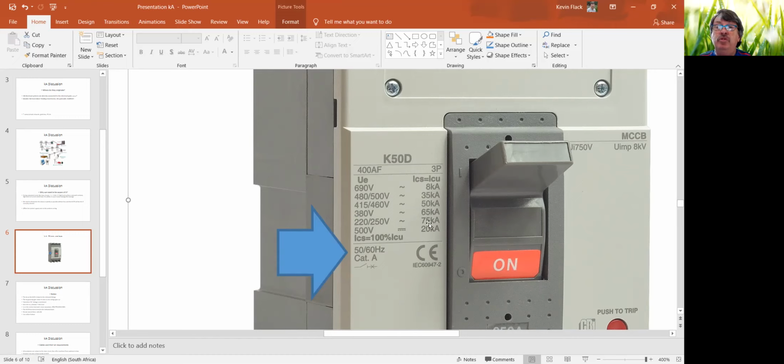And it's very important to discuss this, because what does this really mean? It means if we have a short circuit level available at a certain point in a panel board, and it is, in this case, 52 kA, you can see here that you cannot put this breaker there because it's 50 kA. It is underrated in terms of that. However, if you only had 35 kA in that same panel board, and we talk about 400 volt networks there, the 50 kA would be fine. You can overrate that. Obviously, the performance is there.